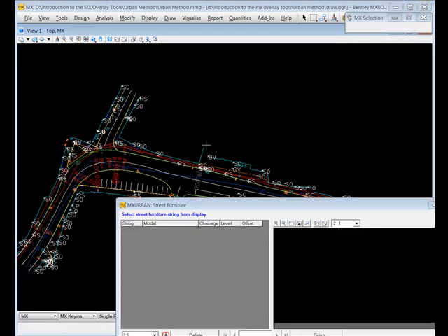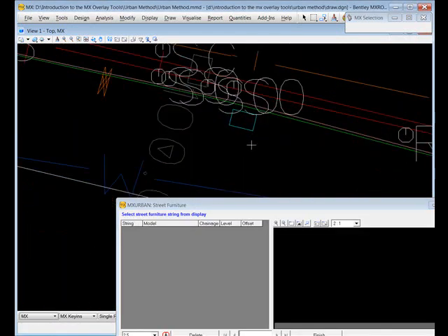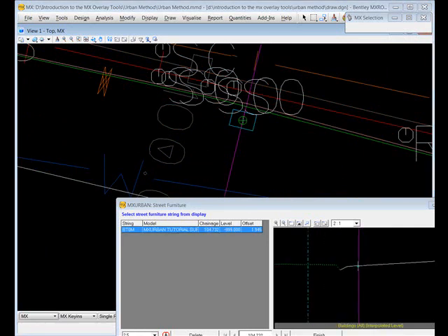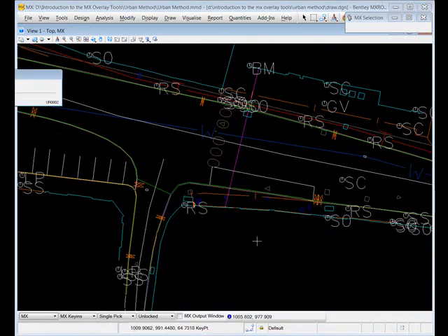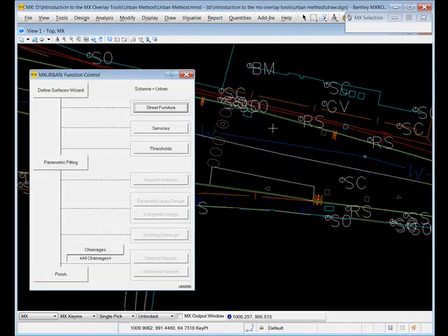The street furniture option lets me specify pieces of street furniture just by picking them from the plan view. We see them in the cross-section view here, and these let me check that the design, for example, is above each item of street furniture. If I can achieve that, it'll be cheaper to construct the scheme than to take the cover off the street furniture item, lower the chamber inside it and rebuild the cover. So I might want to try and make sure that my design is above the street furniture. There may well be occasions when I can't, but it's something that I might want to check.